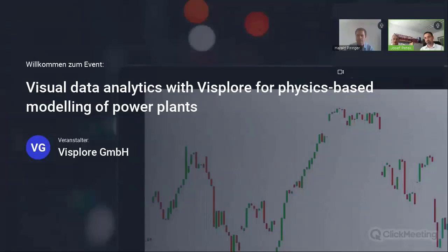So the degradation lines or trains need to be evaluated either by statistical process control or, as they are lines, by visual inspection. A single deviation should not trigger an alarm, but if there is a clear trend and a clear deviation over time, then certainly you can trigger an alarm. And from the trend lines, you also see the rate of degradation.